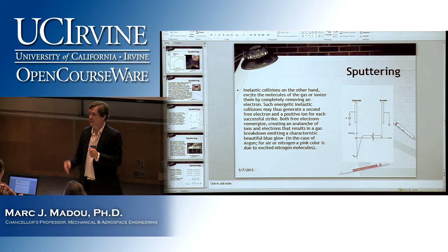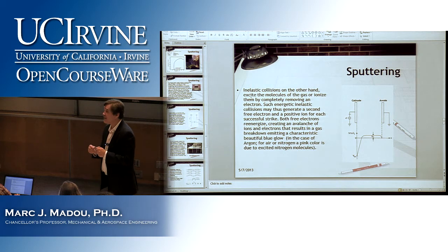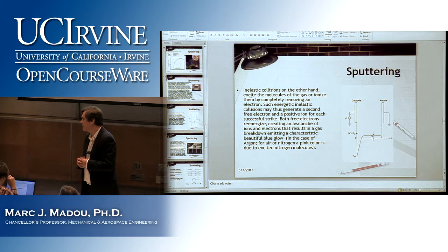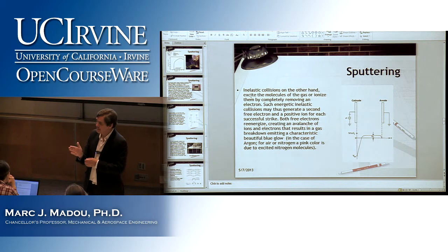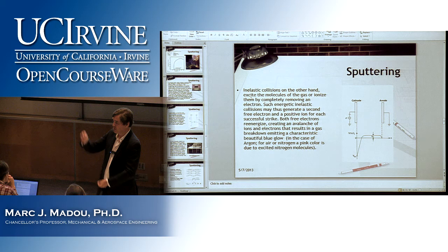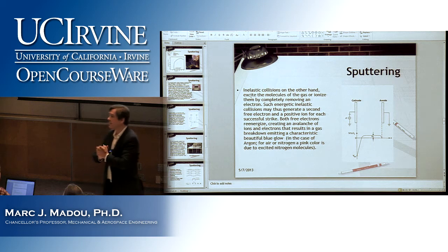Electrons there? Sorry? There's a lot of electrons there? That, again, has to do with it, and you're kind of right, and you can mimic that effect with a capacitor. The reason is the electrons in front of the cathode move faster away than the ions. So you have a big charge distribution. You have a big space charge there, and that's where the voltage drops. Even without a capacitor, in that case.